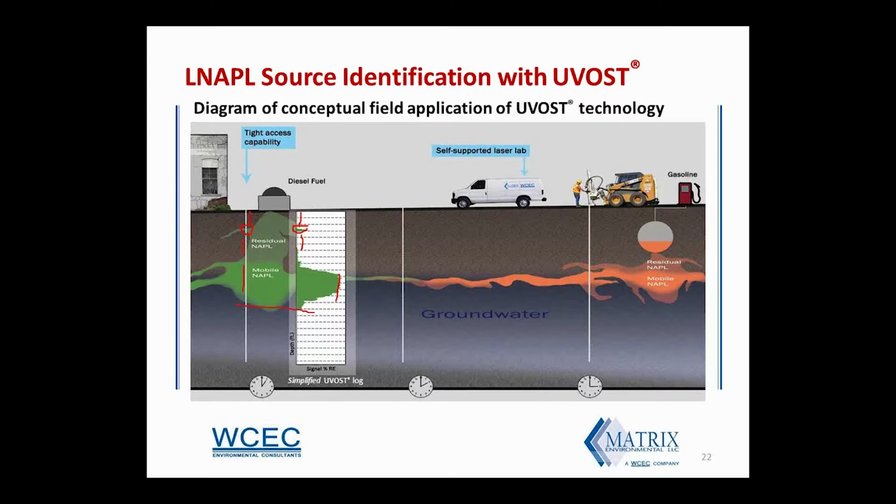and immediately below, that lines up maybe, coming down this way, then there is, again, no instrument response. So we typically recommend going about 10 feet below the water table, or what you believe to be the greatest depth of LNAPL, to ensure that the LNAPL is adequately characterized with depth. We also recommend at least 1 boring at every site go about 20 feet below the anticipated depth of LNAPL. And this is because our experience has shown us that it can be a lot deeper than initially expected. You just may be surprised when you do this. And if that information was missed, it could have some pretty serious impacts on the effectiveness of your remediation.